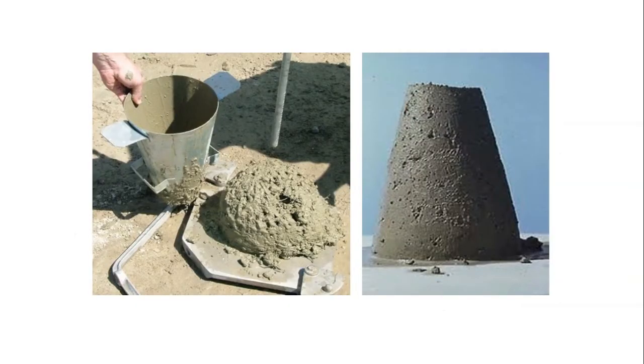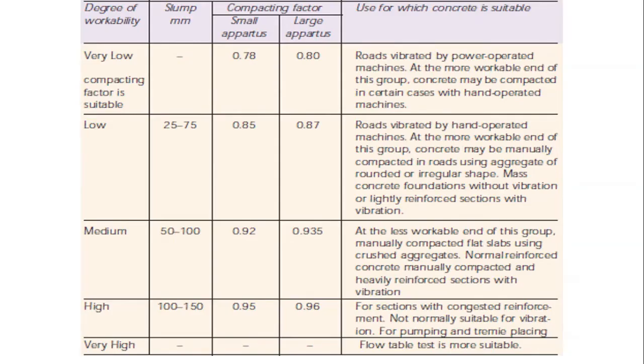Of course you can see different concretes show different slump values. This is the tamping rod, by which you tamp the concrete. 10 centimeter. So based on the value of slump, you are going to define concrete as low workable, medium workable and high workable concrete.